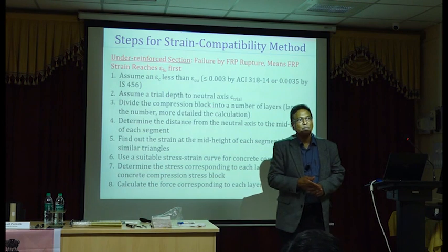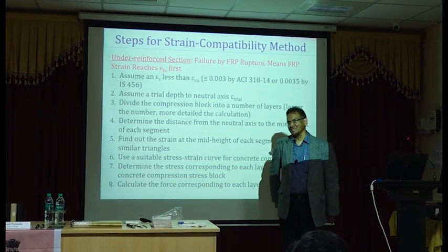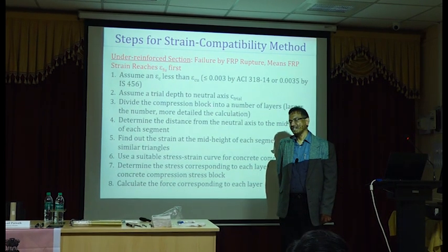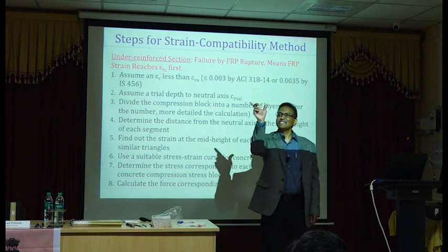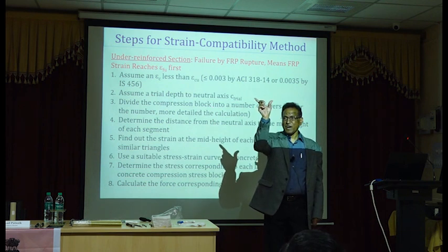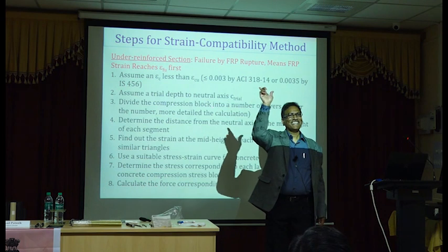That's one thing, but that's right. To limit the neutral axis depth. Yeah. So that we can ensure the under-reinforced section. Right. But remember, we talked about these strains in compression at the extreme compression fiber, right? In case of an over-reinforced section, that's defined. We know that.